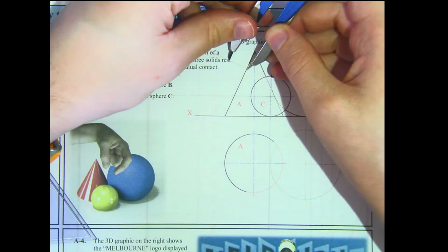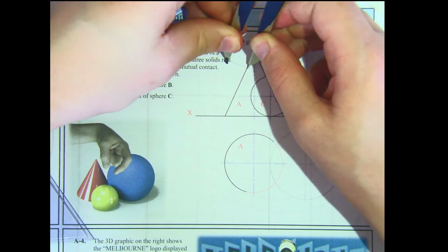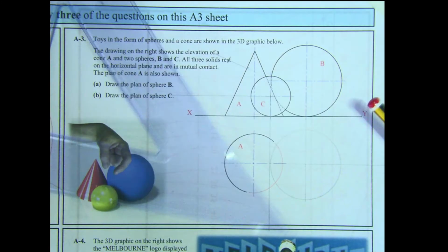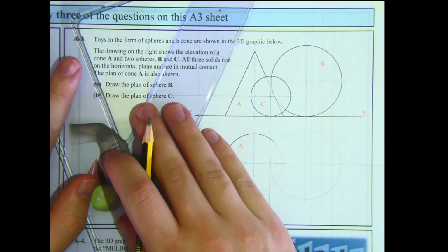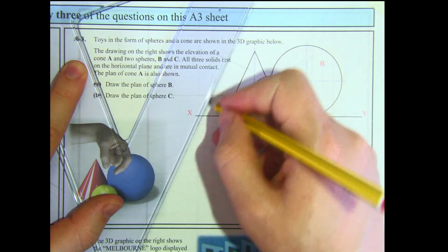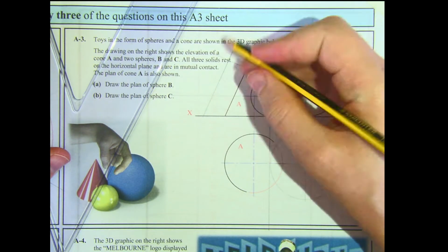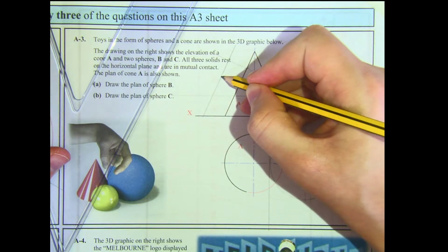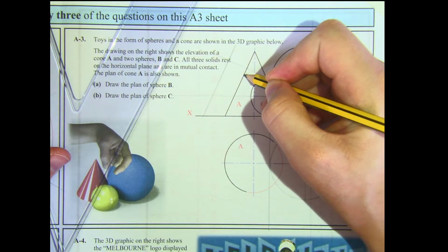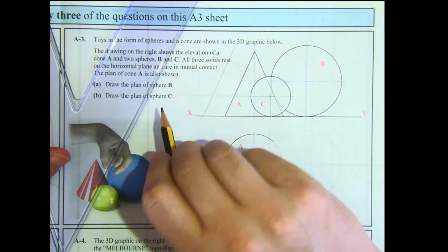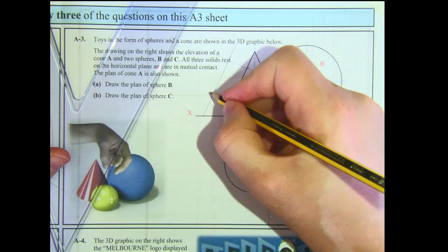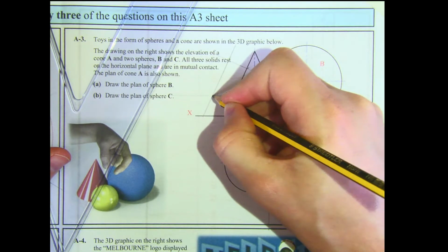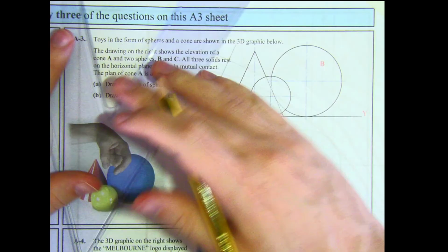I'm going to add that onto the line that I just marked a moment ago. So again, going parallel to the side of the cone. Everywhere along this line I could draw a sphere of radius C that would touch off of the side of the cone, and anywhere along this horizontal line I could do the same thing where it would touch off the XY line. Where they cross each other is a point that will do both. It will touch the side of the cone and the ground line.